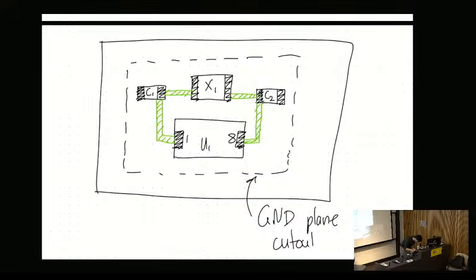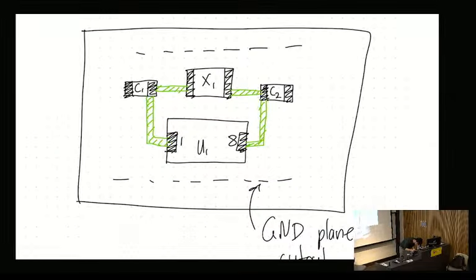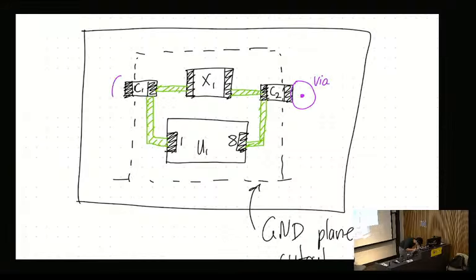Oh, actually, good point. There needs to be a ground plane where we need ground. Underneath most of this crystal, we don't actually need ground, but you made a good point. We actually need ground on this capacitive leg here and on this capacitive leg here. So I can't make the ground cutout there. It needs to be just before. So maybe there. That would be good enough. And then here is where our via would go. So that would be a via to ground.